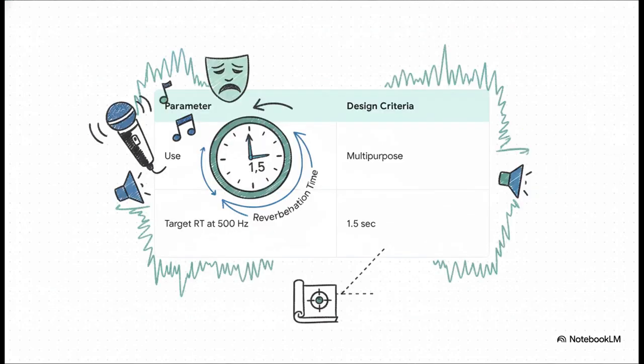Okay, time to define that acoustic bullseye I mentioned. Since this is a multi-purpose hall, for talks, for concerts, we need a good balance. We are officially aiming for a reverberation time of 1.5 seconds.